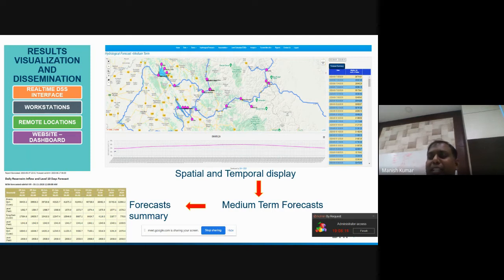When water from Satluj enters into India, that area is Khab, where we calibrate our model. For the downstream area we had lots of point stations, meaning ground stations, and we used lots of satellite based information and created this rainfall runoff model, then a hydrodynamic model. We are forecasting these flows at certain points on the river system and tracking the flow here.